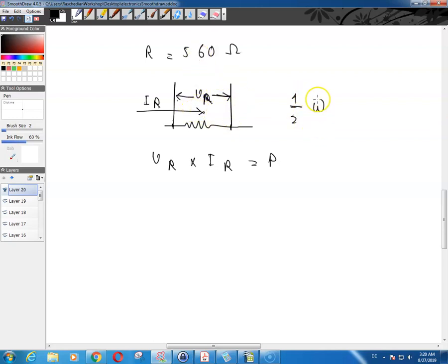And then of course you never choose a resistor whose power rating is below the power dissipation which takes place in the resistor. So you need to be careful about that. Basically, resistors usually come in these packages, and there is a standard for the power dissipation capability of these resistors.